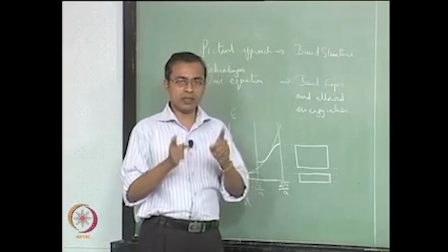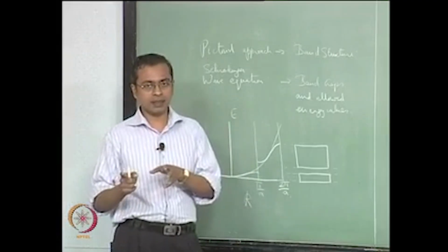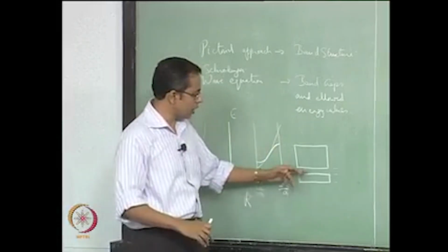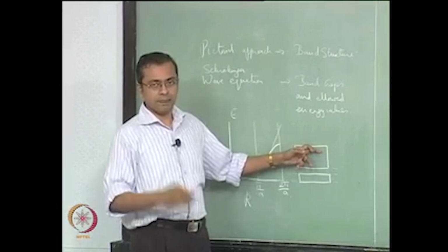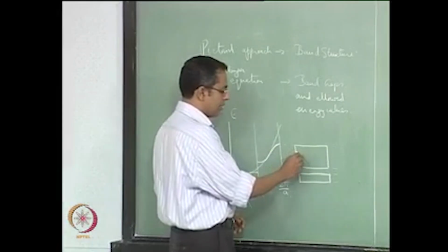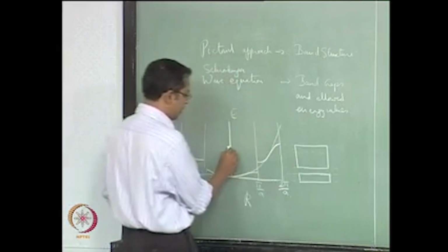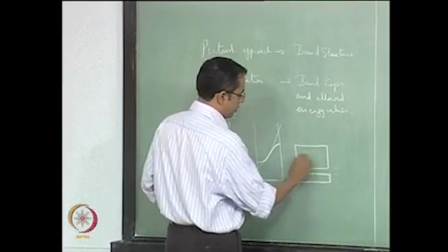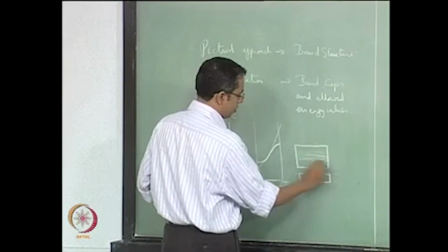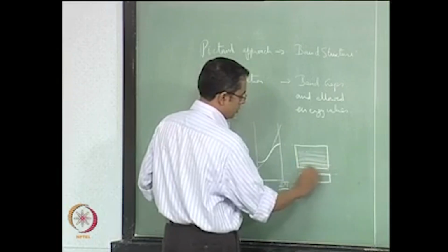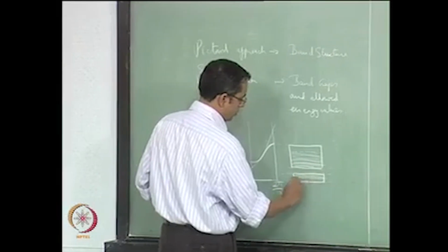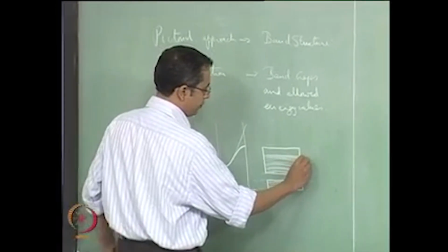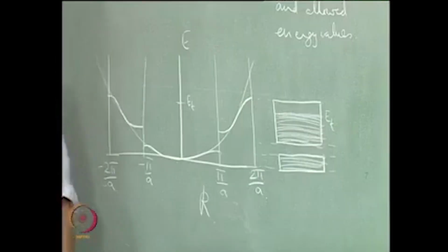So that is why we have the density of allowed states and the density of occupied states. Of those that are allowed, some up to some level is occupied. So these are all allowed values in the system, based on where the Fermi energy is, which is the highest value of electron energy in the system, which let us say arbitrarily I am setting here. If I set this as EF, then up to here everything is occupied. All these discrete energy values are occupied up to this Fermi energy EF. Above this you have vacant space.